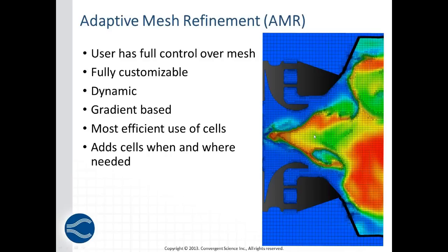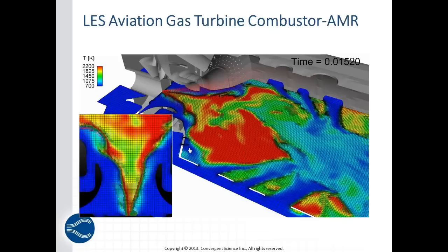And that happens at every time step. Once again, you also see the embedding that we have applied around certain geometric features where it gets a little finer near those geometric features. And because we're using an octree approach, you still have excellent quality of that mesh near the boundary. And once again, we're using a cut cell approach near the boundary.